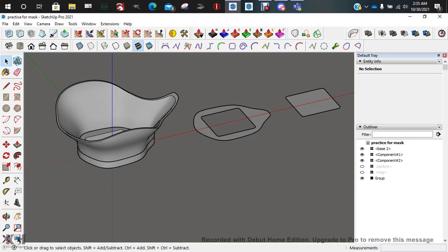This is 3D printable. Last time I did it, I printed one, including the grid and everything, in 2.5 hours on my CR10. And that was at 0.24 layer height, and it's 60 millimeters per second. So, it doesn't take too long. You could print it in flexible TPU, but I don't recommend that. I recommend PLA or PLA Plus.